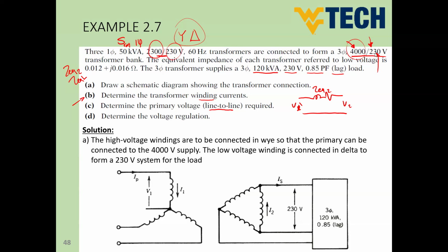In order to do that, guys, what should be the connection? We mentioned, guys, if the volt of the three-phase is similar to the volt of the single phase, this means the connection is delta. And if the volt is different, the connection is going to be Y. Because, you know, for Y connection, you have the line volt equals √3 times phase volt, and in delta connection, phase and line voltages are equal.